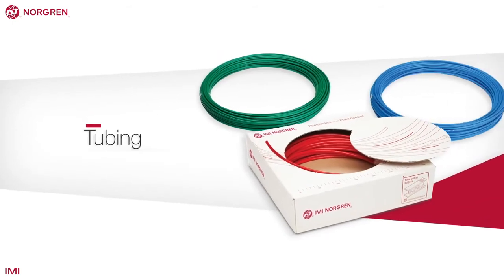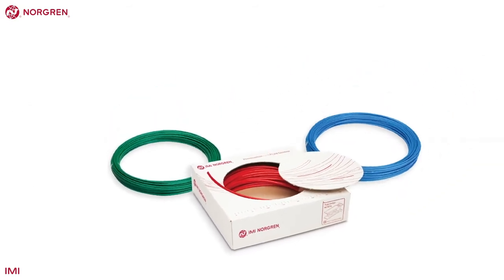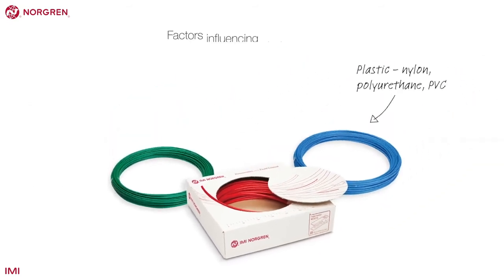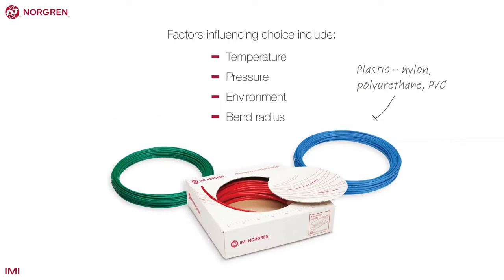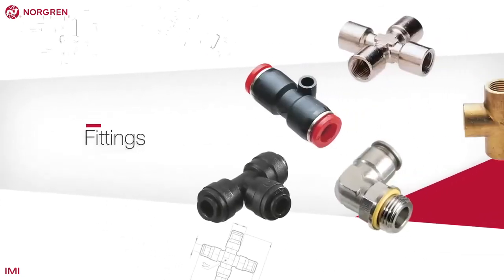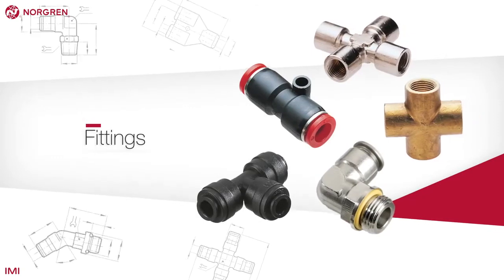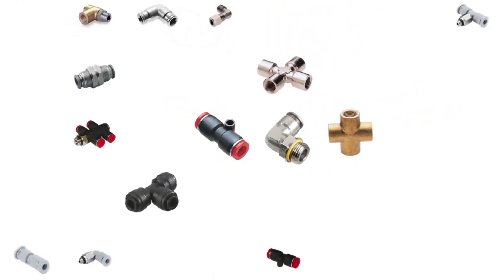It's usually best to start with tubing, as this can dictate what type of fittings are required. Typically, tubing will be specified as either plastic or metal, with a number of factors influencing the choice, including the environment and application. Although it can be a little daunting to begin with, selecting fittings is generally easier than other parts because there are fewer things to contemplate.